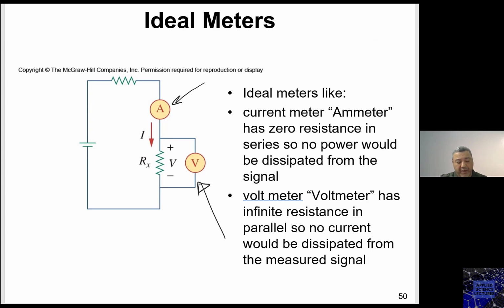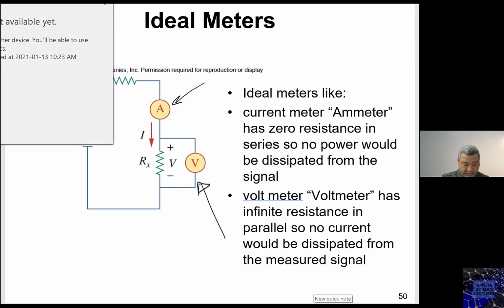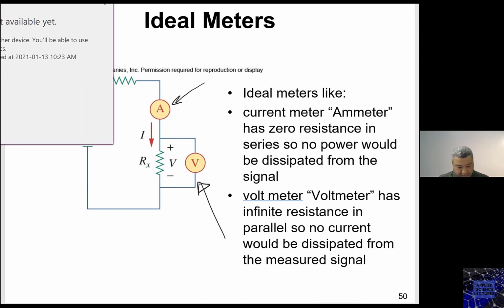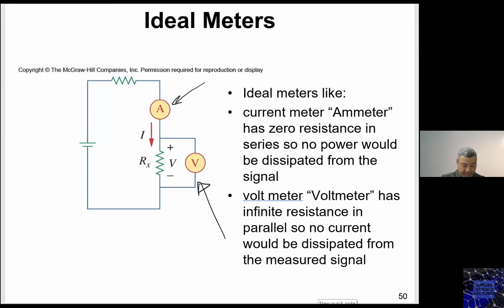So the ammeter, we have it in series. So if we have a circuit here, I have to break this circuit to insert the ammeter.